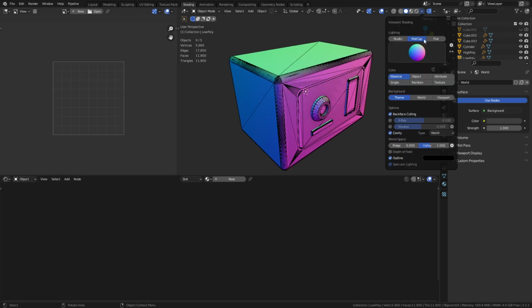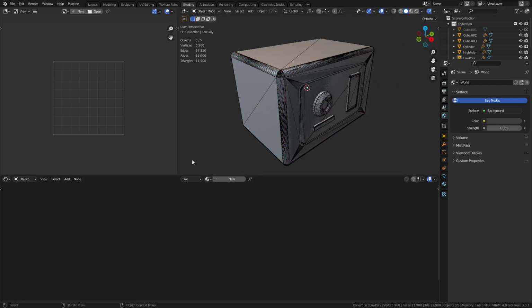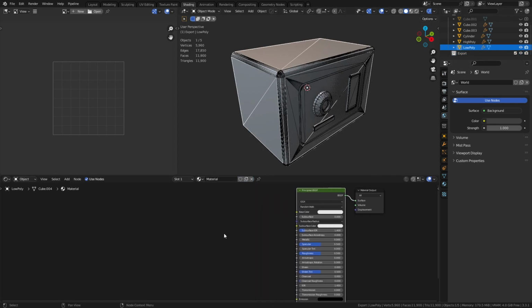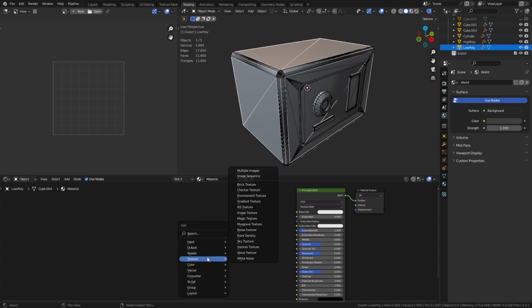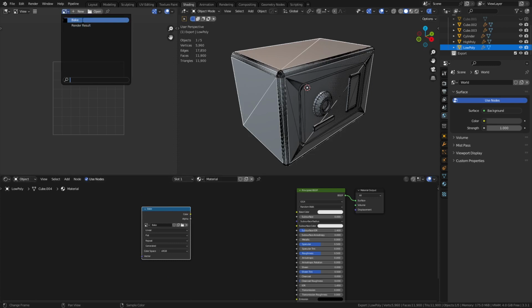We're going to go back to just a regular matte cap real quick, and not that that matters, but we want to select the low poly here. Create new. This new material we create, all we're going to do is press Shift A, create a texture, image texture. We're going to create a new image texture. In this case, I'm just going to call it bake, and we're going to do a 1024 for this video. Okay, and make sure it's selected. All right, we're going to go up here, switch to bake.